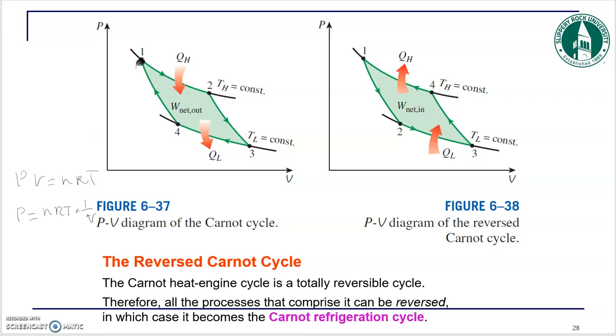This is a cycle, and remember, the boundary work of a system is the area under the curve, so that's the W net out. Now this is not the net work that I'm drawing here; this is the work that the gas does from state 1 to state 3. The gas receives some work from state 3 to 1, which is this area, in color.